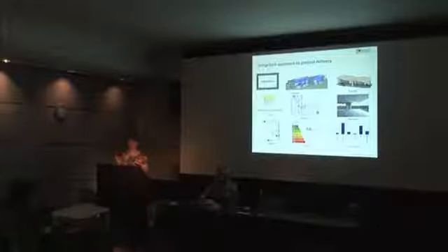do that as well. Now, there are reasons for that, which again we will cover later on in a bit more detail. But I think the key point here is, if you're going to be trying to implement this integration between the two, you need to be very careful in planning your model for export. In simple terms, what I'm saying here is keeping a stripped down version of the BIM model for export, okay? So not one with all the door handles and all the light fittings and the balustrades and every possible bit of detail in it, but something much, much simpler, okay? And this will become more apparent as we go through.